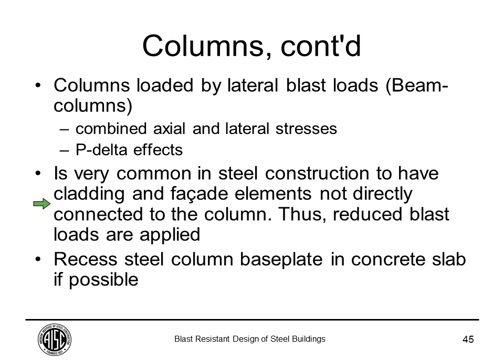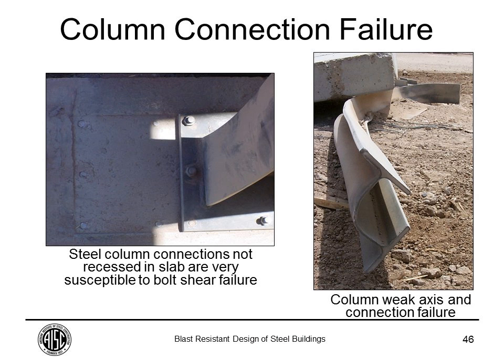One of the main considerations for design of blast resistant steel columns is the base plate. Generally, you want to make sure that you recess the plate because that could be the weak point. Again, we're trying to develop the full dynamic capacity of these things, and if you don't have a recessed plate, you can have a bolt shear failure, as you can see here in this test.